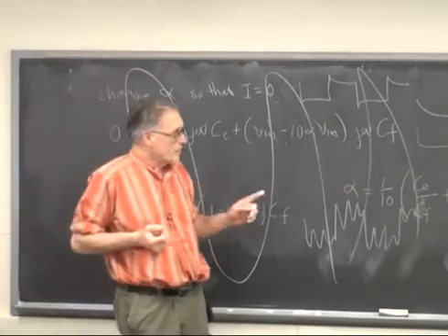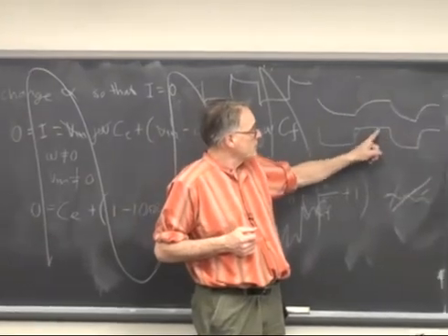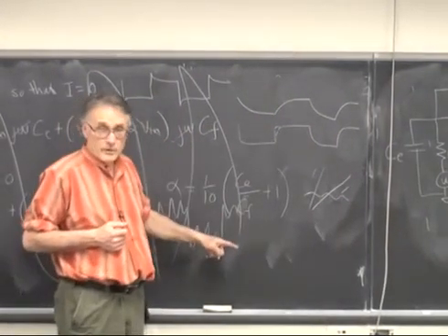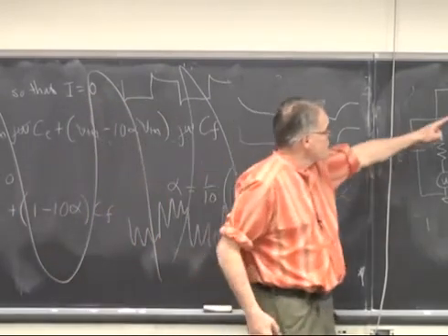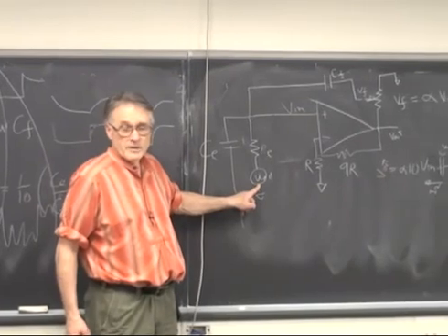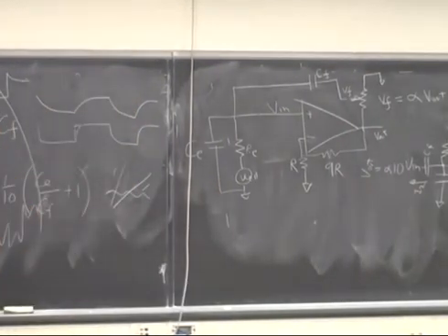One small problem with this system is that if you accidentally turn up the feedback to the point where the system is oscillating at full amplitude, this becomes a current injector into the cell and blows up the cell membrane. In fact, some commercial amplifiers have a thing called a buzzer on it.